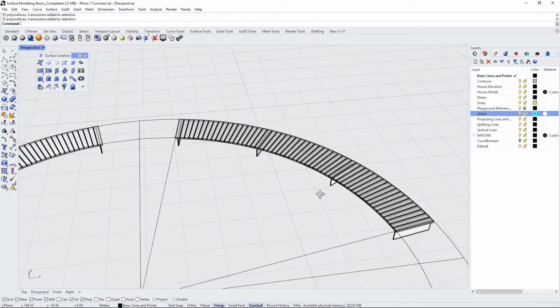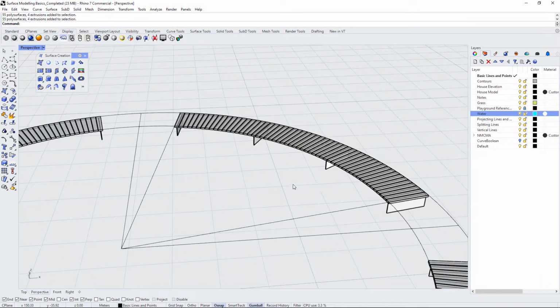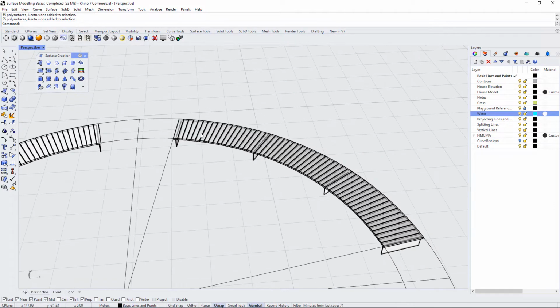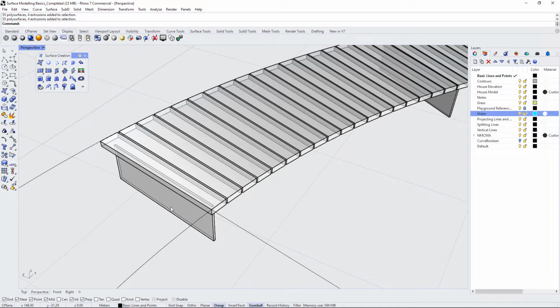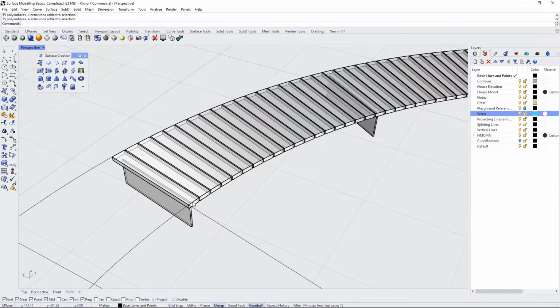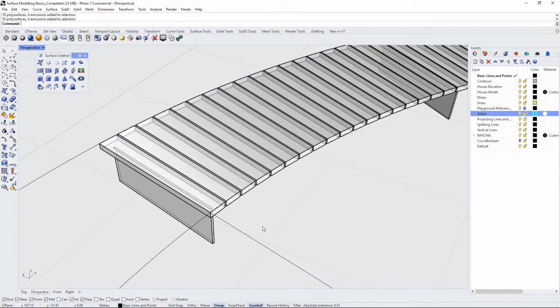Now, this is usually something that you do when you have a detail in mind. So I would have been working off of a drawing that probably outlined different wood pieces. And as you get more knowledgeable in the field, you'll understand what standard dimensions are for certain things. A bench is usually between 45 and 50 centimeters high. That's a good sitting height. Standard piece of lumber is a 2x4, but we also have 1x4s or 1x2s and other dimensions. This one, I think, is a little bit wider.